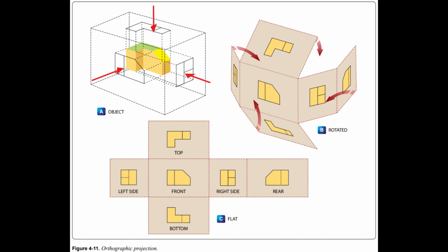If the right side view is shown, it will be to the right of the front view. If the left side view is shown, it will be to the left of the front view. The top and bottom views, if included, will be shown in their respective positions relative to the front view. One-view drawings are commonly used for objects of uniform thickness, such as gaskets, shims, and plates.